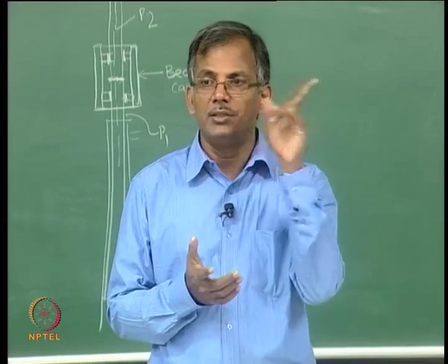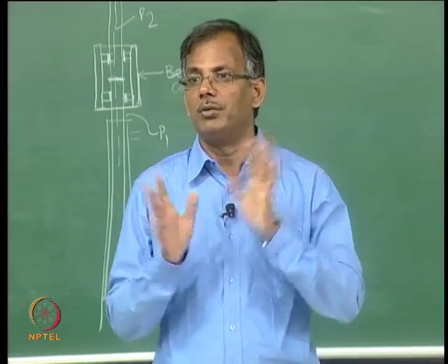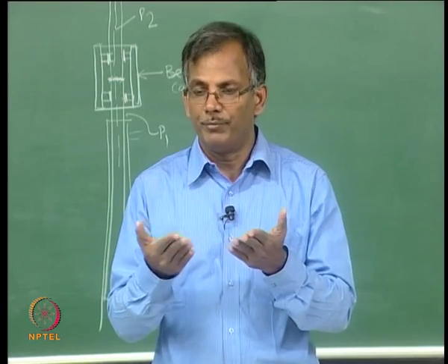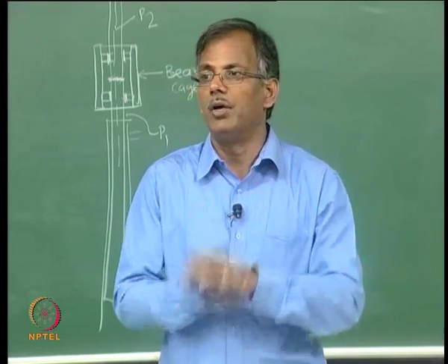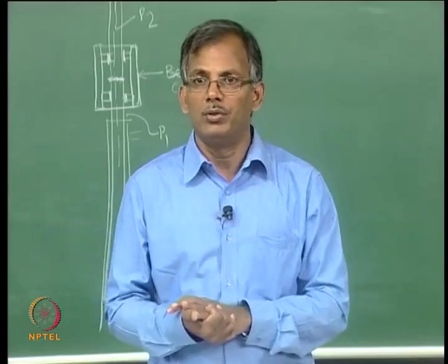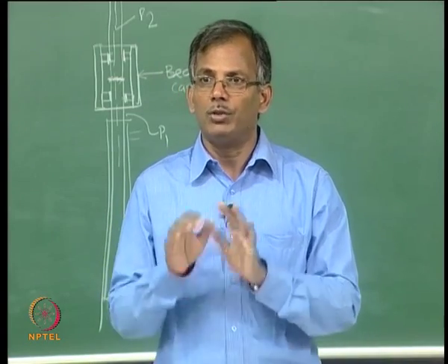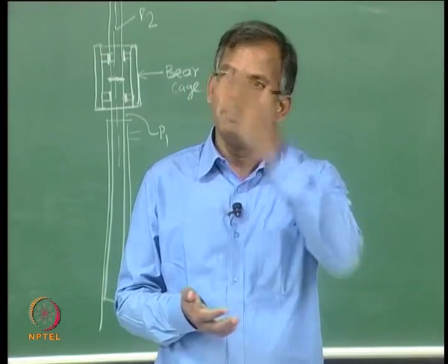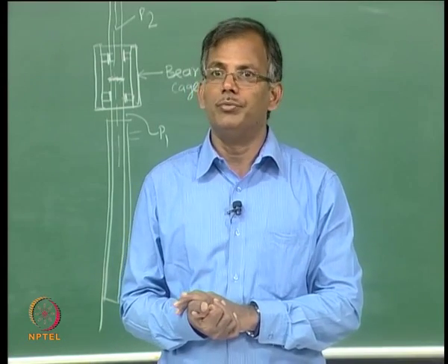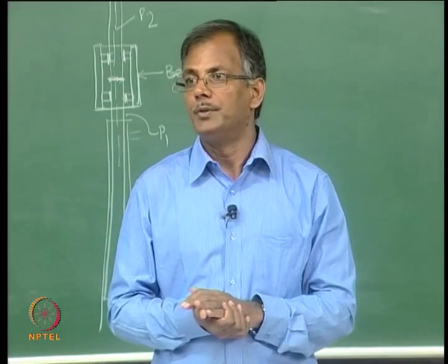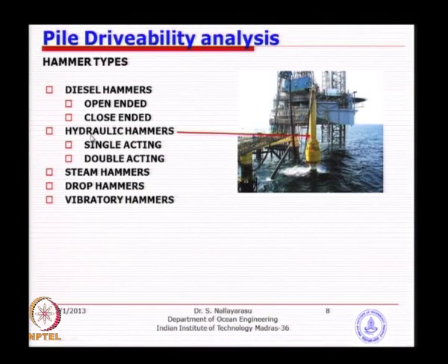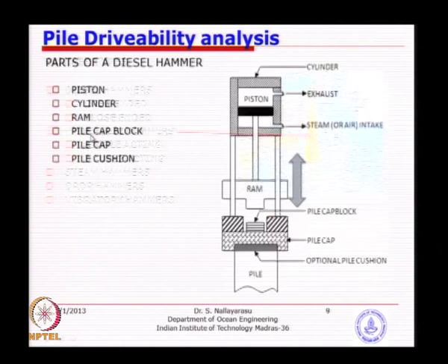For example, if you take a diesel hammer, several times it breaks down, and one of the problems is that replacement becomes a problem. Onshore, today one hammer breaks down, you can bring in another hammer tomorrow, whereas offshore, once it breaks down, the project is almost gone, because the next time that you can bring the hammer will be next few weeks, which will not be tolerable. So that is why even if it is main pile driving, many times we use hydraulic hammers.